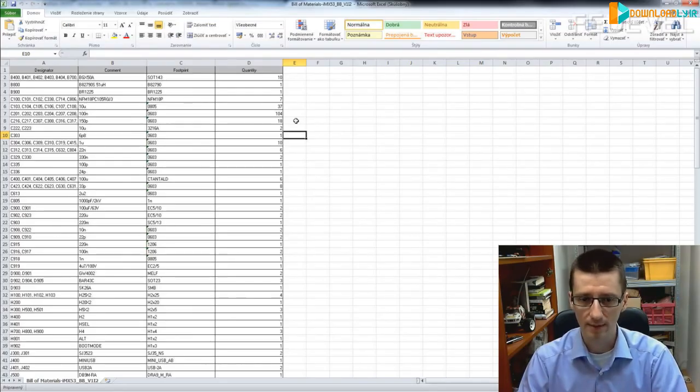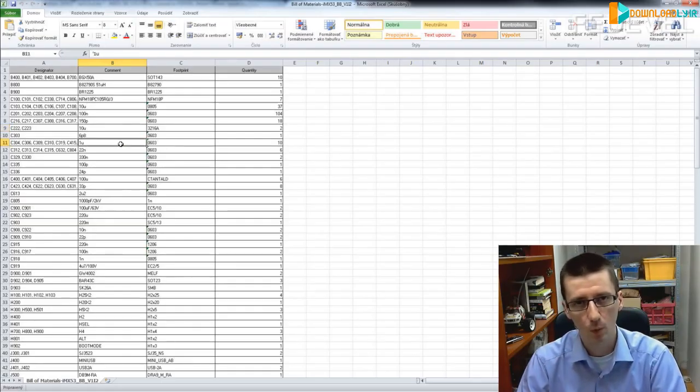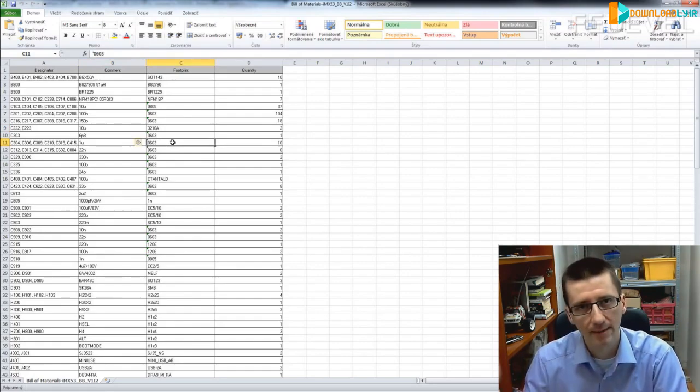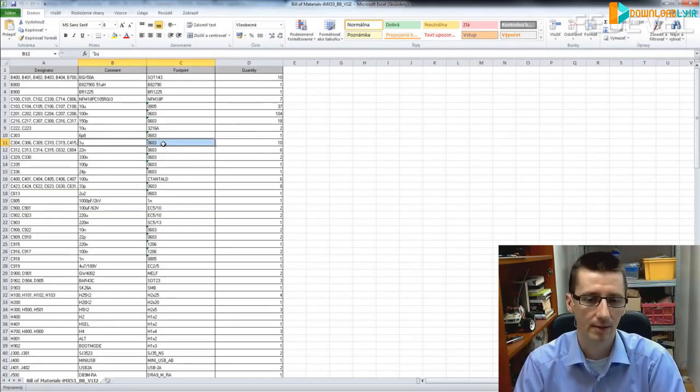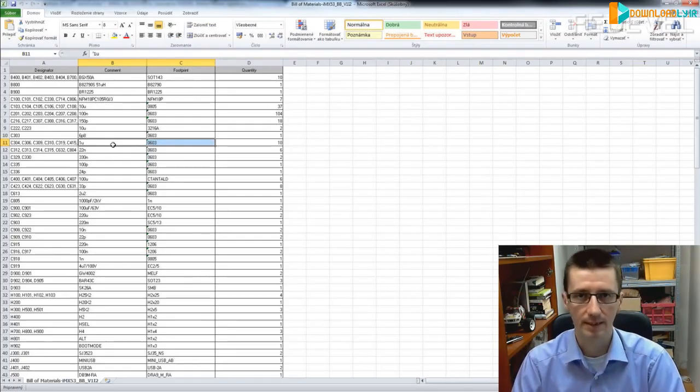If engineers are too lazy, they don't even specify part numbers for components like capacitors or resistors, because they think it's clear from here, yeah, I want 1 microfarad 0603, so buy some. By the way, this is not a full specification of the capacitor. There should also be voltage, and there should also be some properties like, is it NPO, is it X5R, or it's not so simple.